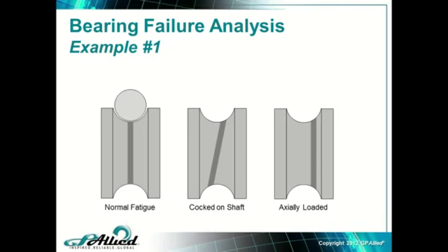The bigger learning point for everybody on this call is, had that organization waited until they could feel that bearing and it was rough, or until they could hear it, or until it heated up, where do you think this evidence would be? Right? These tracks here on these races, that's evidence of poor, incorrect installation practices. It's just subsurface fatigue right now. That's where the evidence is.